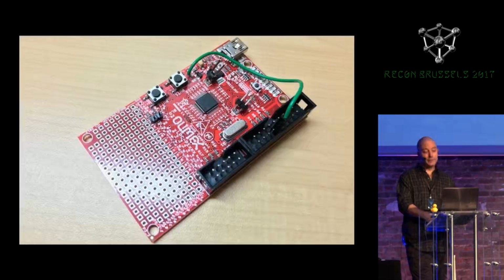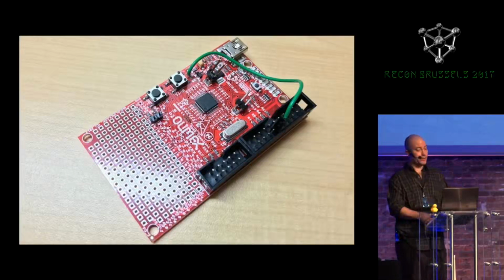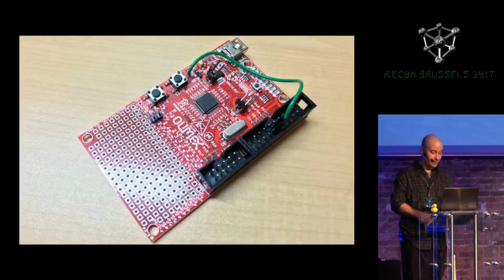And then another option is also to use a pre-made development board. This is an Olimex board for the LPC 1343 chip. This one has been modified a little bit. I've removed two of the capacitors, C1 and C4. These are the filter capacitors on the VDD pins because I'm planning to glitch this chip, and that's going to involve quickly dropping out the power supply, so I don't want those filter capacitors. They're going to be trouble for me.